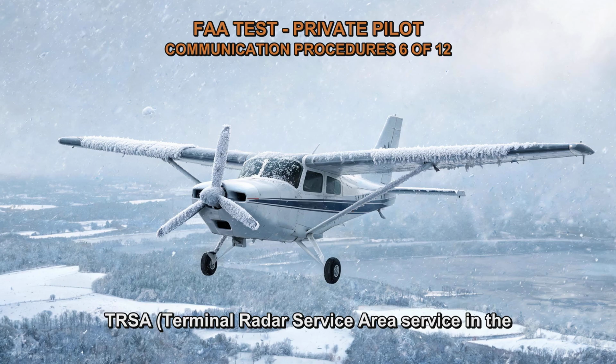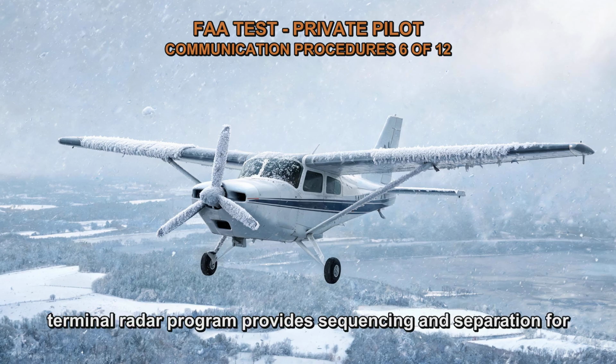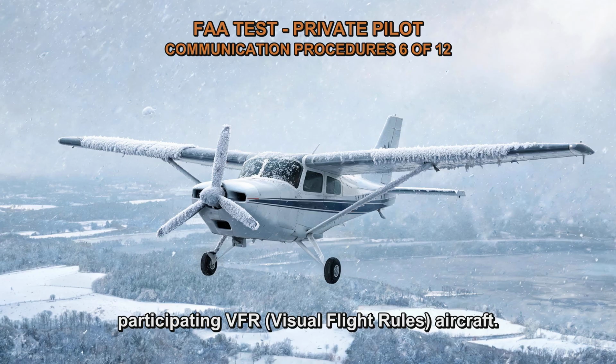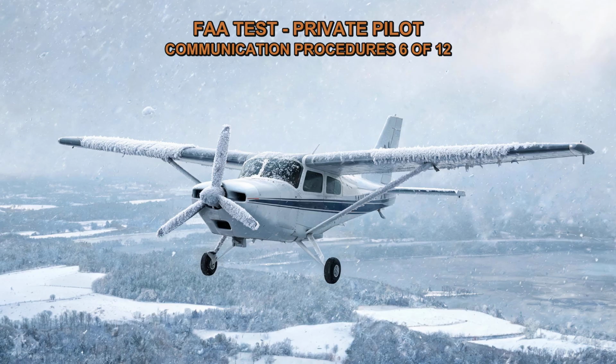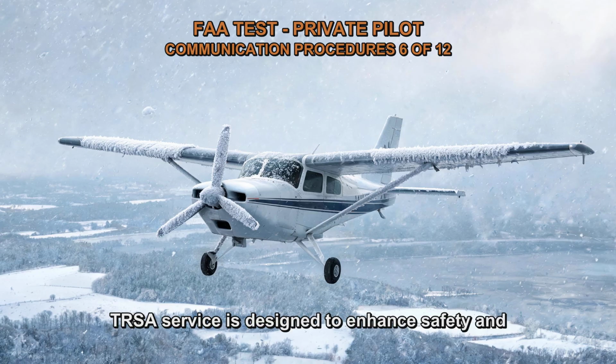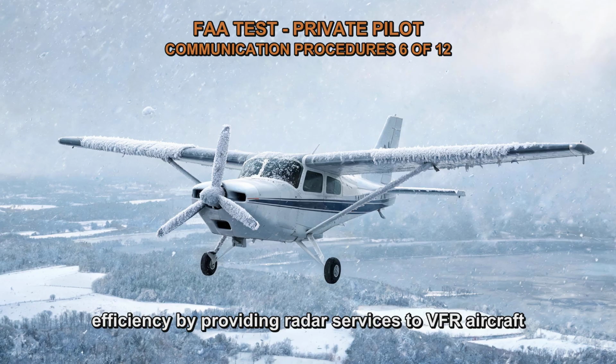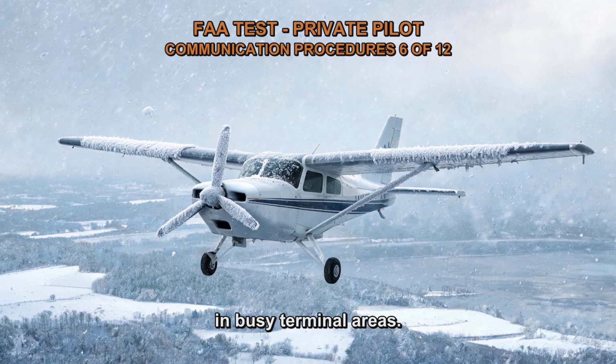TRSA, Terminal Radar Service Area service in the Terminal Radar Program provides sequencing and separation for participating VFR, Visual Flight Rules, aircraft. TRSA service is designed to enhance safety and efficiency by providing radar services to VFR aircraft in busy terminal areas.